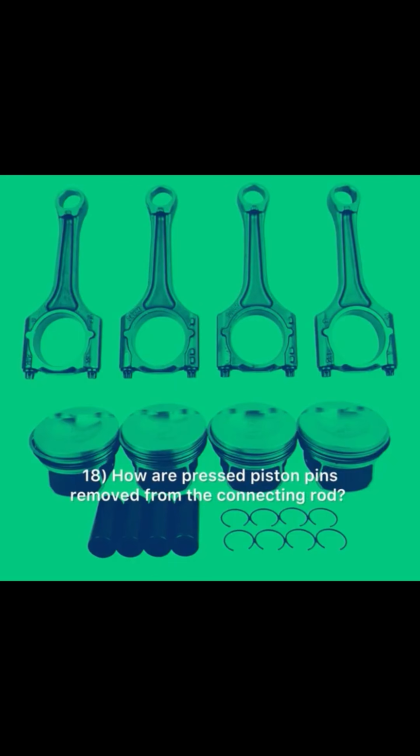18. How are press-fit piston pins removed from the connecting rod? Need a special holder. Use a press. 19. How are pistons cleaned? Pressure washer. Light plastic brush. Solvent tank. Clean grooves with ring scraper or a piece of an old ring.